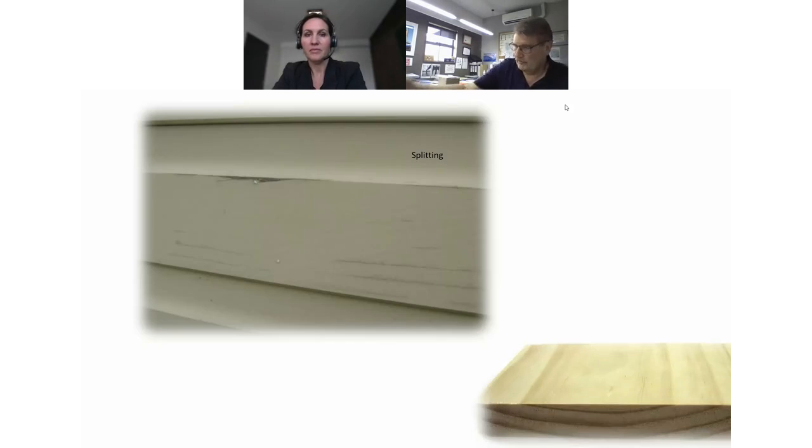Okay, and there's just a picture of, say, a flat sawn board, and I'll put some arrows on it for you. That part there is the late wood grain. This part here is the early wood grain. Now remember, this paint is thinner, half the thickness it's meant to be, so it's not helping in the situation here. And of course, the board got wet.